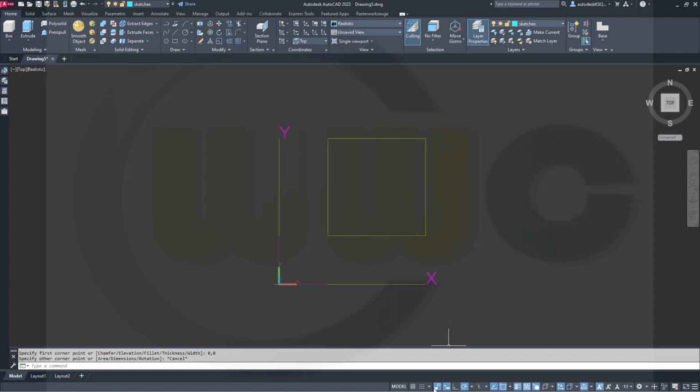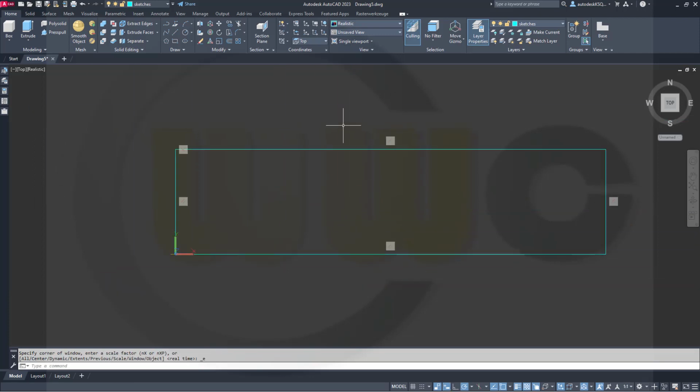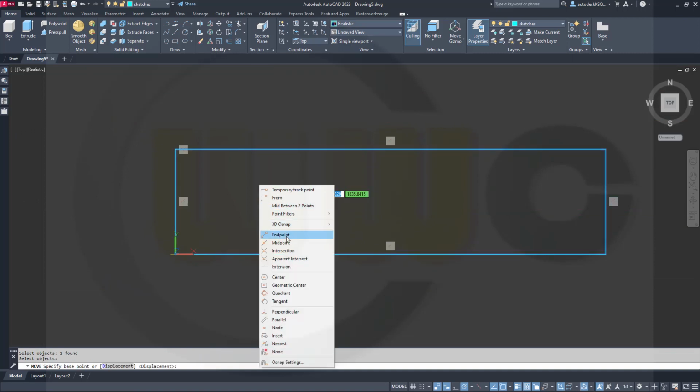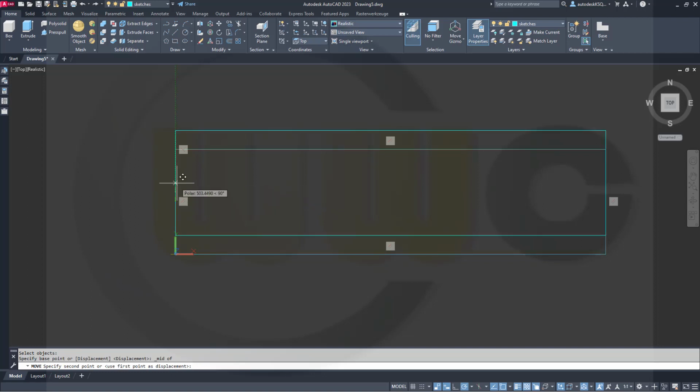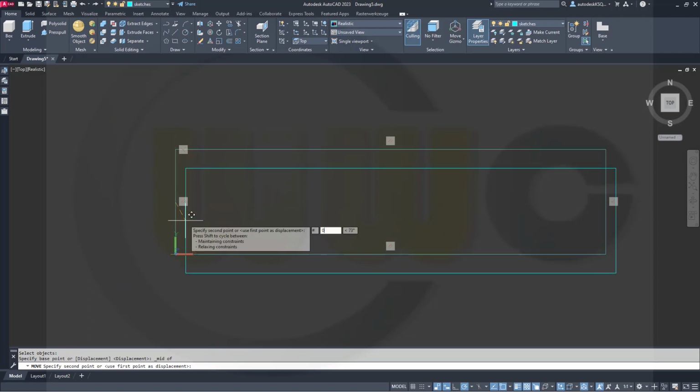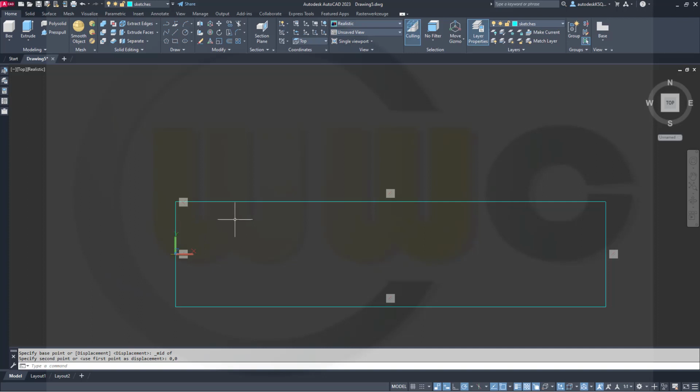Okay, please note that the info constraint switch is on. So I want to start with a rectangle from 0,0 up to 11,250, 2,760. Double click. Then I want to move it. Right click, and the base point should be the midpoint here, and it should go to #0,0 like that.